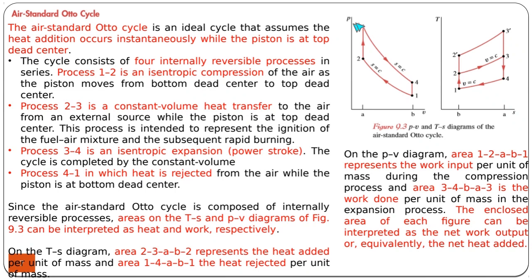Then, because of the pressure that has increased substantially, this pressure applies a force on the piston by moving it down, which creates the work. So this is the useful work. Then, at the end of the expansion or work process, the gases are exhausted, but in this case, there is no exhaust, it's just cooling of the gases to the initial position. So we have the compression of the gases, which means we have to put some work in it.